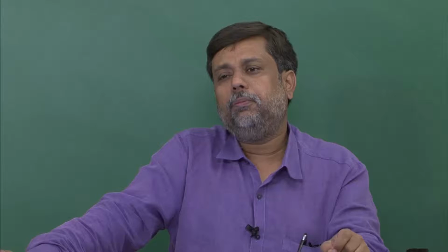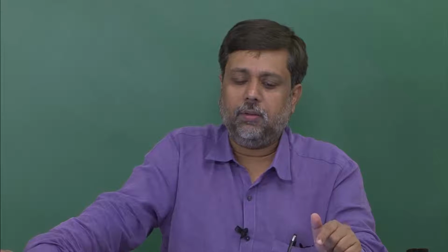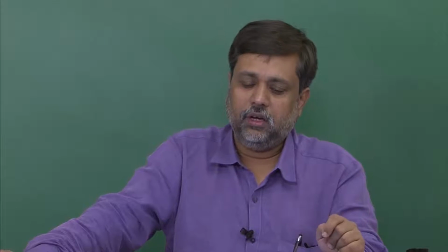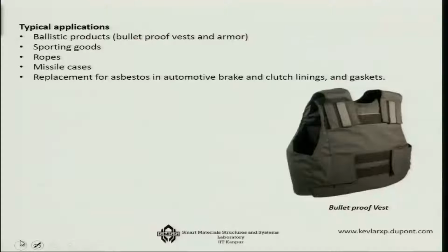One important thing to keep in mind is that in terms of fibers, glass fiber is inorganic in nature. Carbon fiber, well, you may call it inorganic or organic, but definitely the aramid based fiber is an organic fiber. That organic fiber is polyparaphenylene terephthalate or similar such fibers. So that is about the Kevlar fiber.